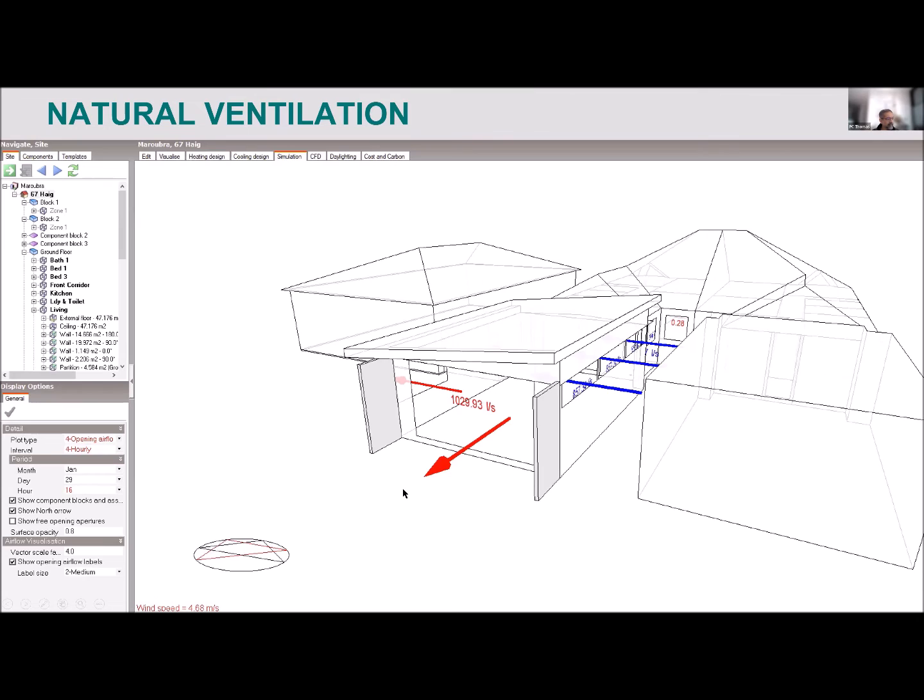And there's a particular reason why I chose this graph. Typically, when you're looking at natural ventilation analysis in any textbook, you will see that the arrows are such that the air comes in from the lower windows and leaves from the upper windows. This is exactly the opposite. Air is coming in from the higher windows and leaving from the bottom. And that's because of the direction of the wind, okay? And that's what Mansi was showing you in those weather graphs.